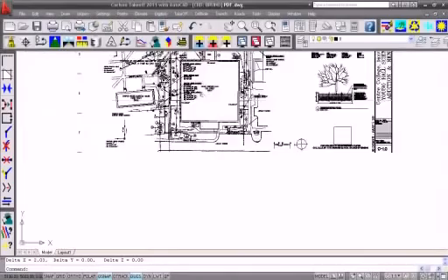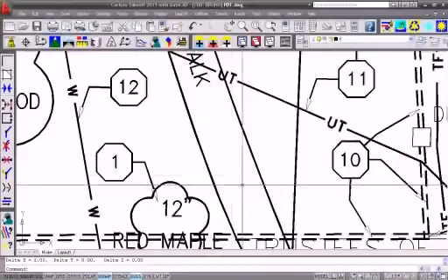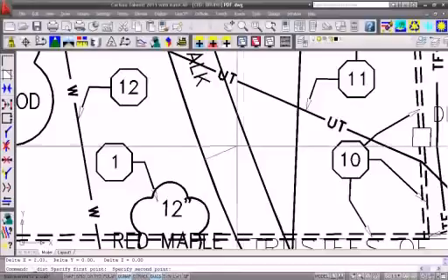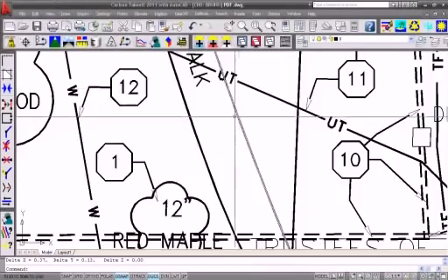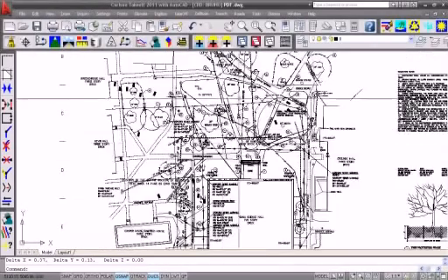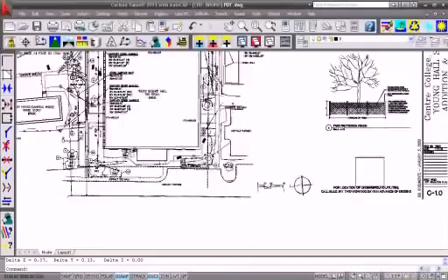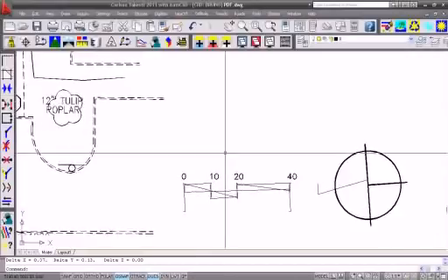All my volumes would be way off. Just to get an idea, this asphalt sidewalk here, if I ran that same command, standard distance, across here, it's saying that sidewalk is less than half a foot wide. So obviously that's incorrect. We need to rescale this drawing in order to get accurate quantities on it. Question. Yep. You'll most likely have to do this with every PDF file that comes in. We've seen that as we've worked with them.